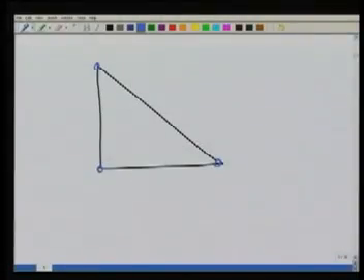Okay. So we will make these vertices. Now again, as we had done earlier, these shape functions, when I project them on the edges of the triangle, they should become equivalent to the one-dimensional 4th order shape functions on this edge. Now one-dimensional 4th order shape functions we had defined in the 1D case.